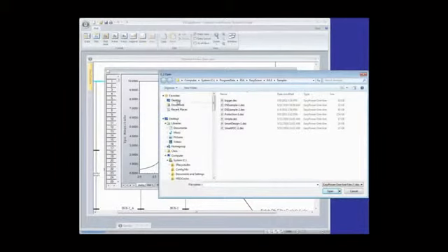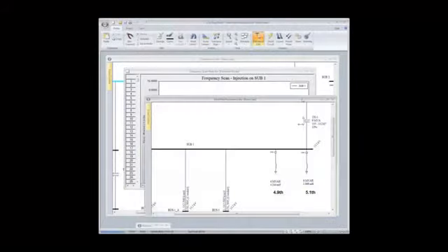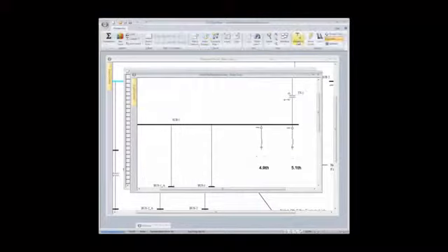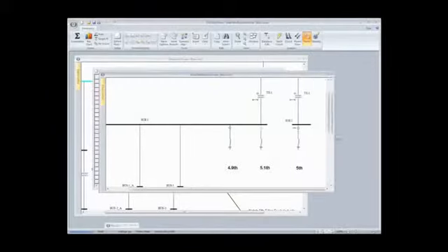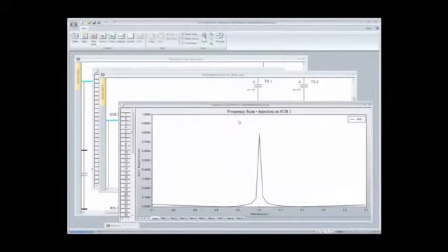If I go to desktop on webinar and interfilter resonance, I have this case here. So let's go into EasyPower Harmonics. Let's put both of these off. Let me spread this out a bit. And I'm going to put both of these right on the bus, and I'm doing a driving point impedance scan. And I zoomed in. I ran my scan in the harmonic options from 4.7 to 5.3, and I show it's right here at 5.